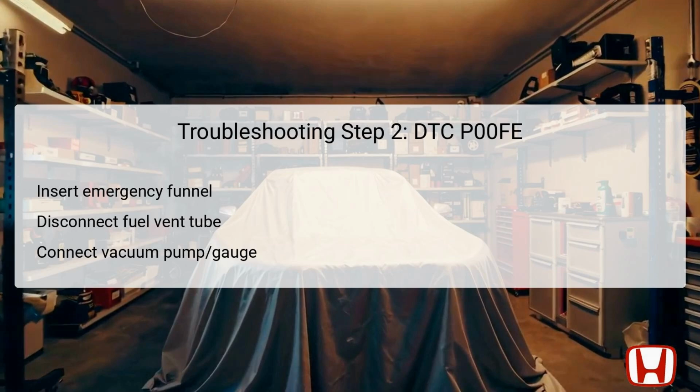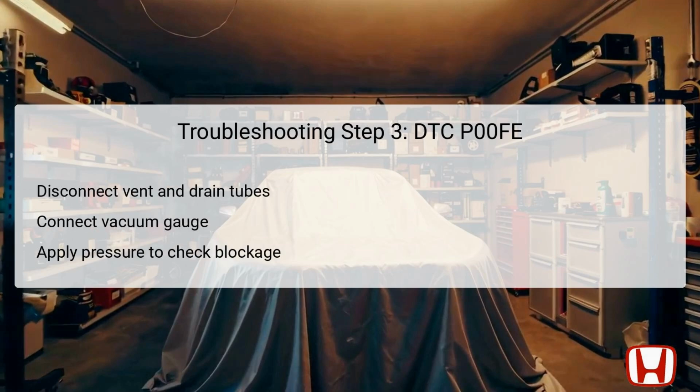If the pressure is not held, it indicates that there is a blockage in the fuel tank system that needs to be addressed. For this third troubleshooting step, focus on the EVAP canister. Begin by disconnecting both the fuel vent tube and the drain tube from the EVAP canister, ensuring you can access all necessary ports for testing.